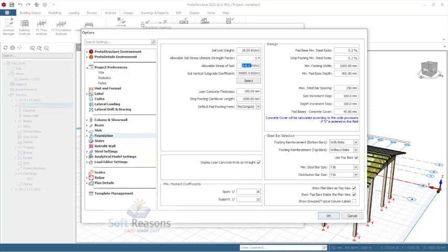Okay, for the sake of this presentation, it takes 160 kilonewton per square meter. All right, so the minimum footing size you can adjust, and then the minimum base depth, you can make adjustment here to 350. Okay, and as well the steel bar spacing. Okay, the maximum you can make it 200. Right, so these are subject to changes. All right, after which click on the OK option.